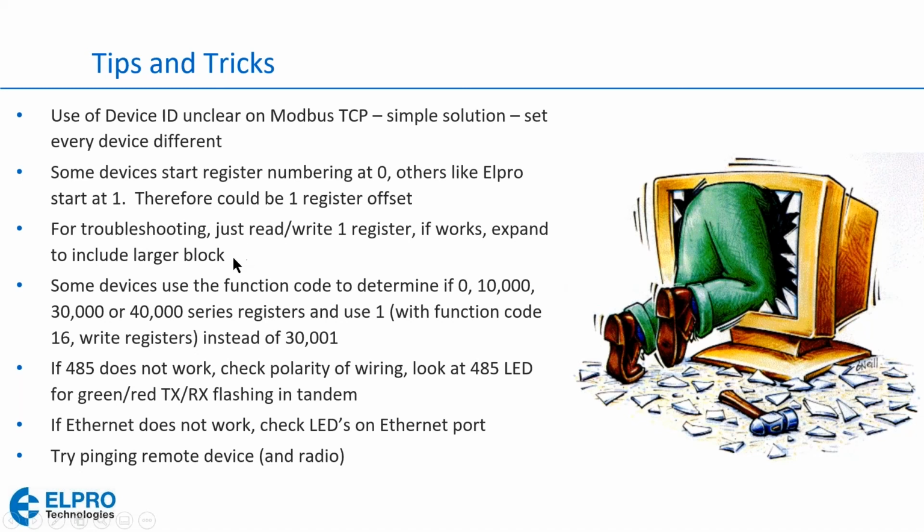For troubleshooting, if you're trying to read a block of registers, keep in mind that with Modbus, if there is nothing in the register, in other words, that register has not been initialized, Modbus will ignore the message and the mapping simply will not occur. If it's a slave device, it will not reply. And if it's a master device doing a write command and there's nothing in the register it's writing from, it will ignore the message. So just keep in mind, there must be data in these registers.